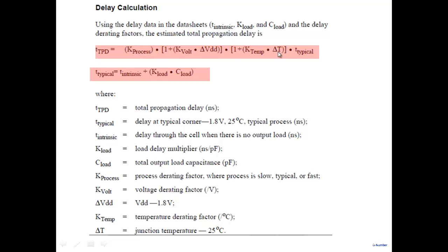So what the manufacturer is saying is, whenever the delay values that the manufacturer is giving, the manufacturer is giving the delay values at a nominal supply voltage, for a nominal transistor, and for a nominal temperature of 25 degrees Celsius. That's what the manufacturer is doing. And if you're interested in some other supply voltage, some other temperature, you want to calculate worst case or best case and all that.